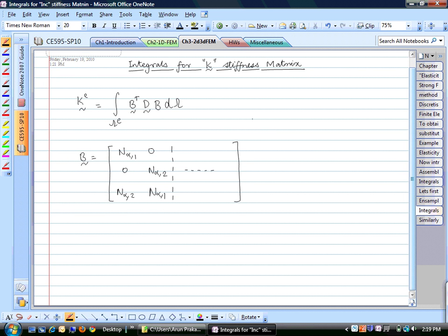And once again, we are going to use the same expression that n alpha of x y is a alpha plus b alpha x plus c alpha y. Therefore, n alpha comma 1, which is the derivative with respect to x, just becomes b alpha. N alpha comma 2, the derivative with respect to y, just becomes c alpha.